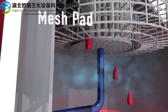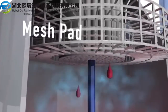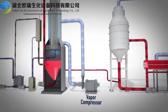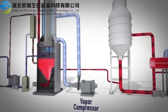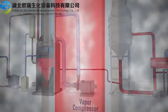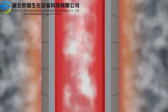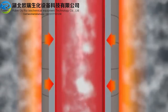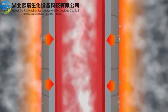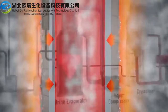Evaporated water vapor flows through the mesh pad mist eliminators. The mesh pad mist eliminators remove any brine droplets from the vapor. That vapor exiting the mist eliminators flows to the vapor compressor. The compressor increases the vapor pressure slightly. The compressed vapor flows to the shell side of the heat transfer tubes of the brine evaporator. The vapor condenses on the outside of the vertical tubes. The condensed vapor flows down the outside of the heat transfer tubes and is recovered as a distillate.